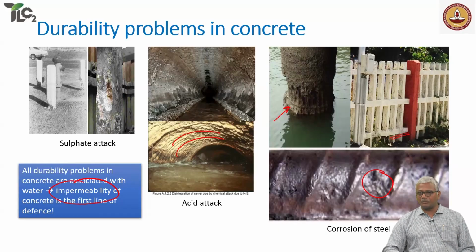In structural design, we limit crack width based on the exposure condition. But then, how often do you actually measure these crack widths? In practice, nobody is really doing it. Only in some specifications is it a mandate to actually measure crack width. But in many cases, we just don't seem to pay any attention to it. So please remember, avoiding cracking is perhaps the most important aspect. I'll touch upon that once again when I talk about durability planning.